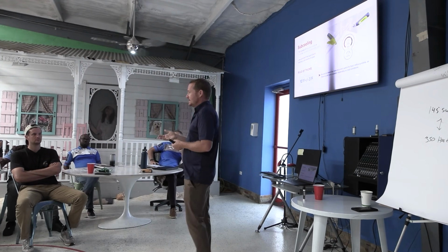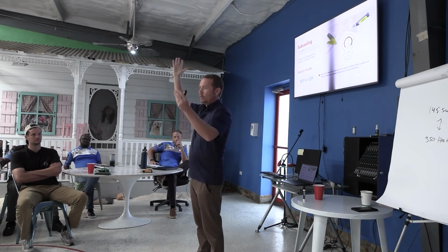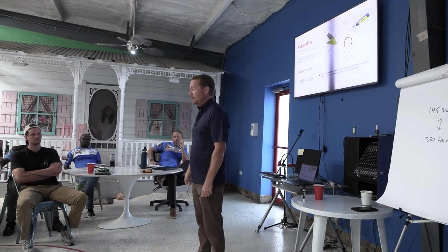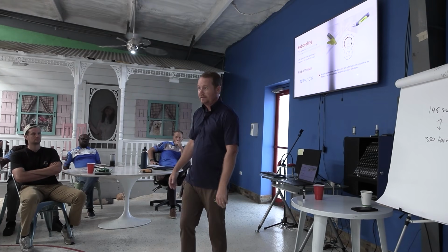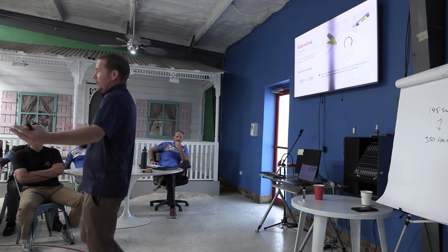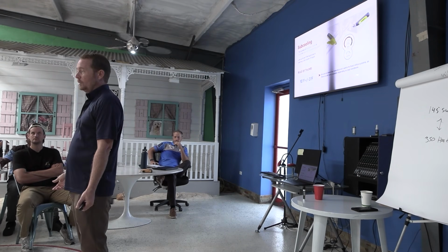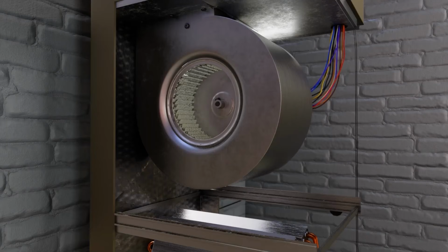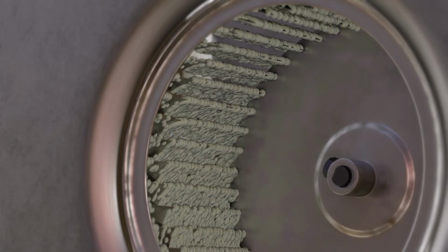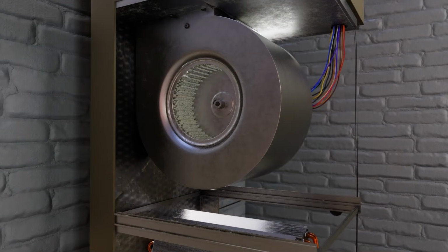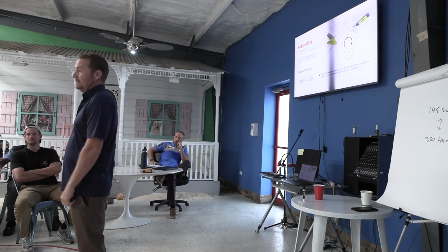And so if you have a system that the fan speed is set wrong, if somebody put some weird blower motor in it that's not the right one, somebody put a blower wheel in it that's not the right one, the blower wheel has crap all over it and it's not moving the right amount of air, yeah, your static pressure will look fine and you will have almost no airflow. A good example would be, you've all seen a really dirty blower wheel before, where it's just completely crusty crudded. If you go up to that system and you measure static pressure, it's going to be really low. It's going to look great.